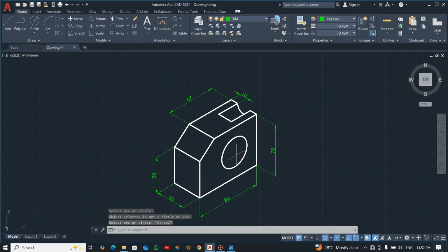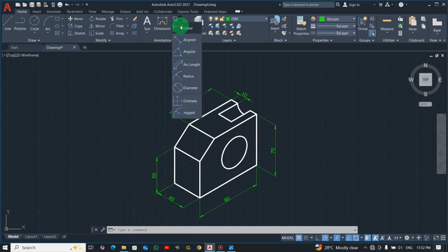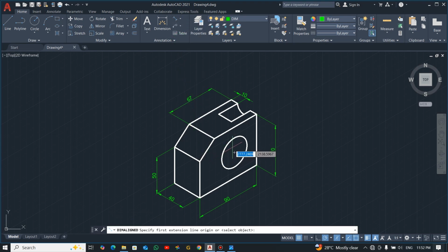So to do that is very simple. You can use the Align for a circle. So let's try the Align. Select Align. Now bring the cursor to the center of the circle, and you see this tracking line always helps us. So I can click the quadrant here, and then bring it here and click the quadrant here and have it. Also you see the angle is different, so let's just leave it like this.